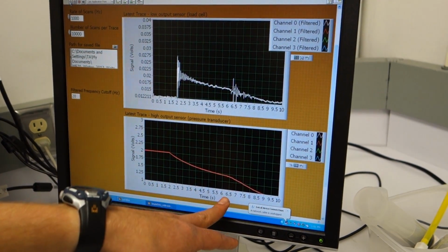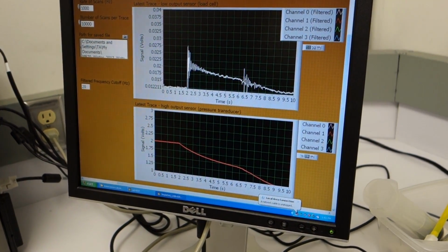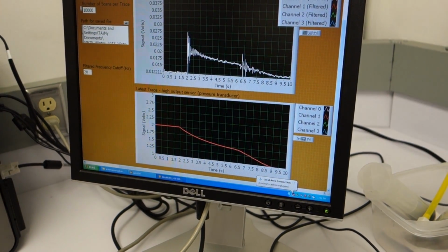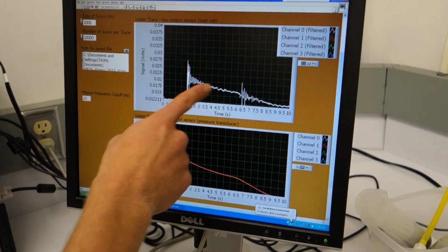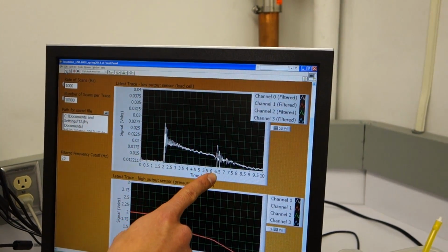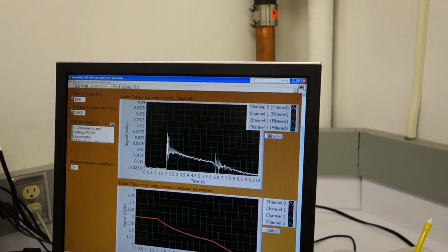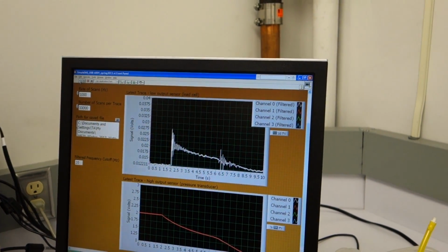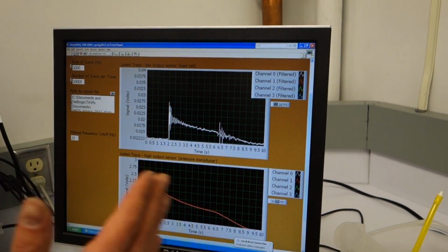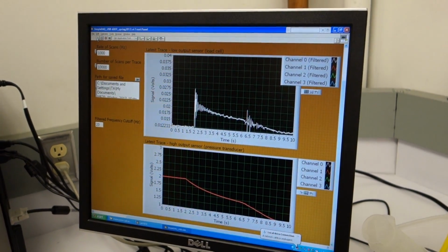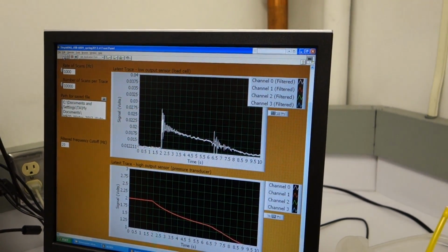And then at 6.5 seconds, what happened there is the water ran out, and we're starting to see an air cannon instead of a water cannon. And the load was released from the device at this point because the force due to the momentum flux of the water is less than that for air because of the density of water. And we see it getting released, and then the same damping characteristics happen, getting it back to equilibrium. So this data will be saved in a text file.